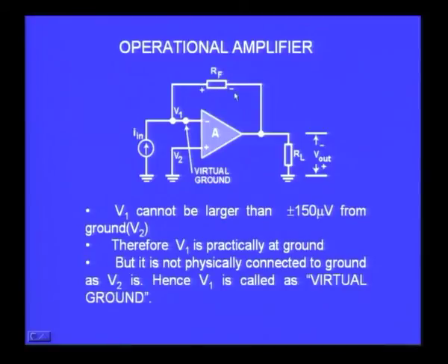So that is the voltage that you will get here, and it is negative. Why is it negative? Because current is going from this end to the other end. So whenever current is entering a point, that point should be negative. Whenever current leaves a point, that point should be a positive point. So in this case you find the current is coming towards this end, therefore this end is lower in potential compared to this potential, and this is 0, therefore this has to be minus.